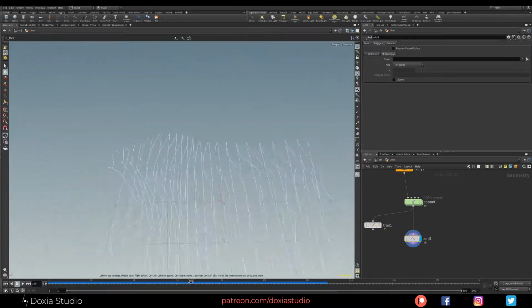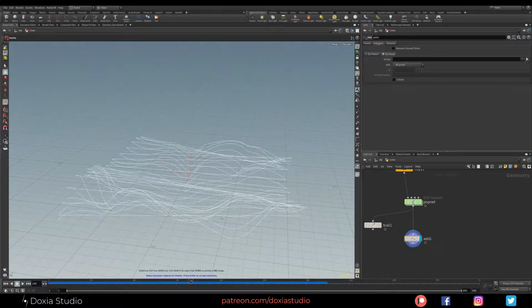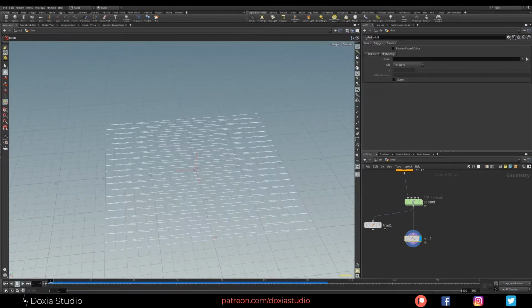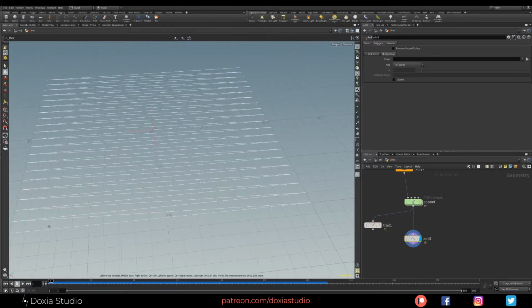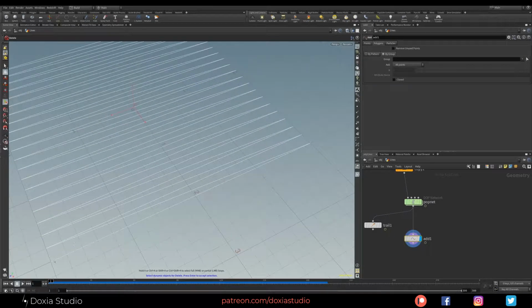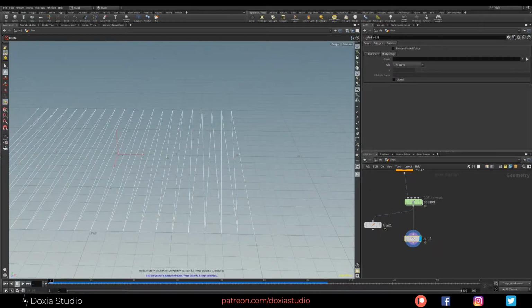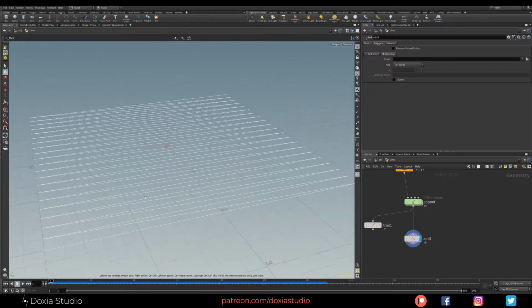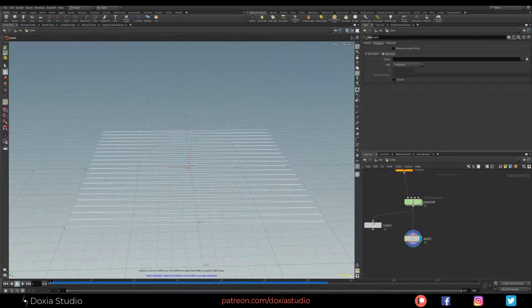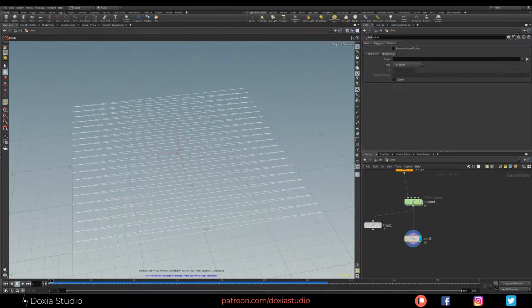Okay, but if we do that, you can see our particles are linked like we want, but we have a spline we don't want. We have this spline here on 2. You can see this is the start, it's going that way, and then the last point on this line is going to connect with the first one on the next one. So we have these little triangles, this zigzag of splines. We don't want that. We want to just connect these particles on the same spline and then stop, then connect this one with this one. We don't want this middle one.